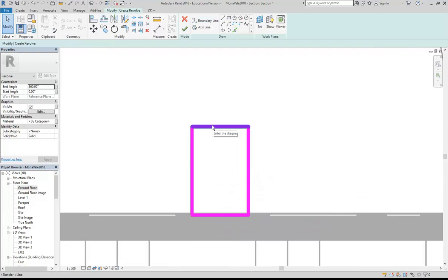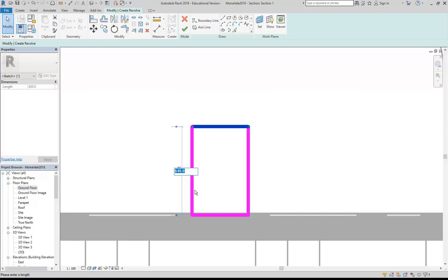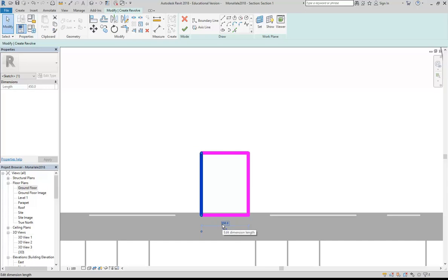And okay, so that's a bit high. I'm going to make it the height of a normal Ottoman. They do vary quite a bit, but let's say 450 maybe we'll go with. And then the width, I want to make this a fairly narrow one, so maybe 800 wide, maybe even less, let's say 700 wide actually. So this has to be half of that width, which will be 350. If it's not clear why it's half, you'll see in a moment.